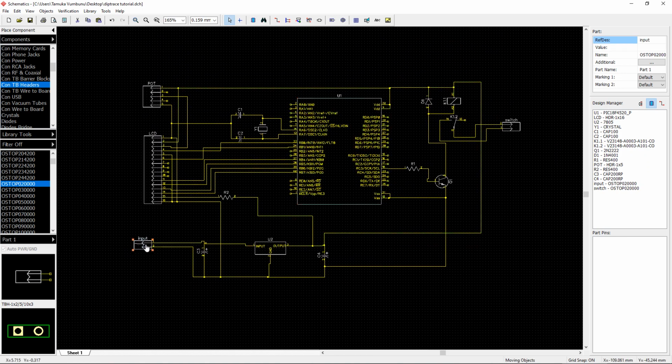For more complicated designs, having done this, you can move on to more complicated designs. So I'm just going to save this and let's just confirm. You now need to confirm that all the connections are where the ground is supposed to be. So from here I know that this pin 2 is ground, so I'm going to move over all of the circuit and see if it's where it's supposed to be.